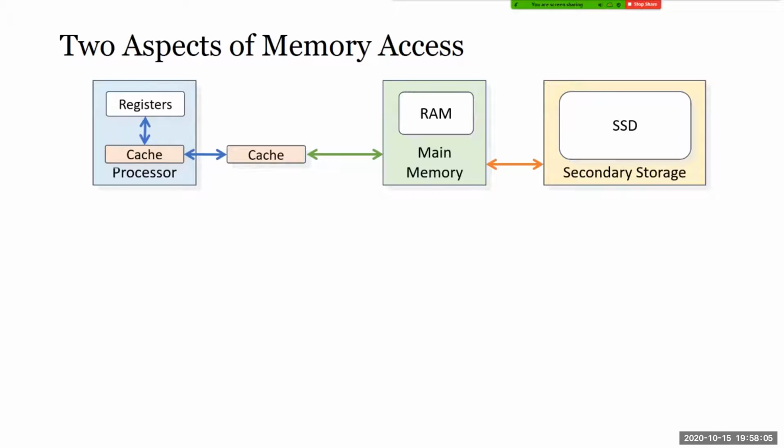It's not just one single cache. Actually, outside here you might have an L3 cache. Inside here you have an L2. Then closer in the register, they call it L1. So they go smaller and smaller. This L3 is 8 megabytes, this is 1 megabyte, and this is only 256 kilobytes. And again, this is our modern processor already. So this is how they do it, right?